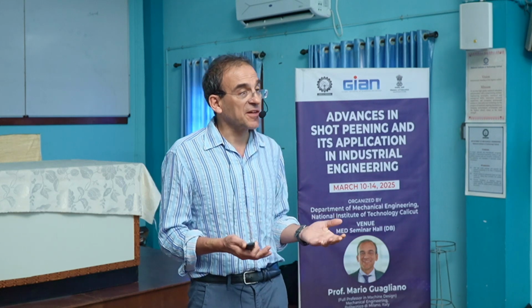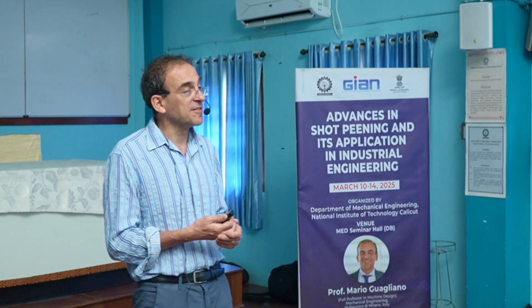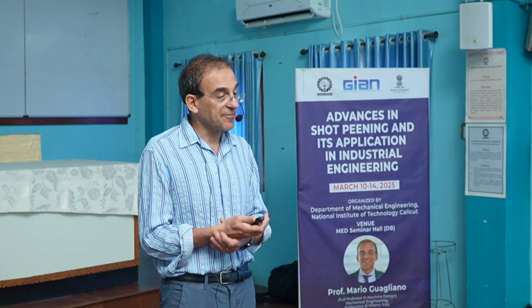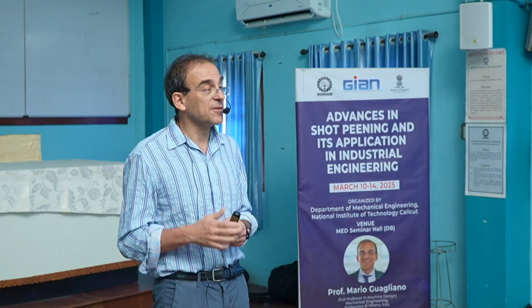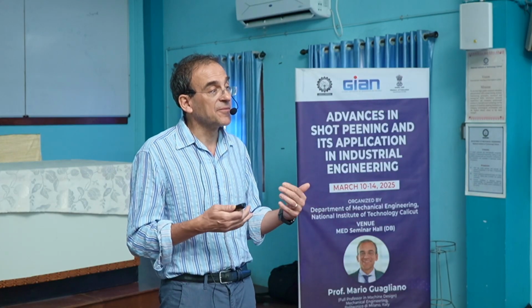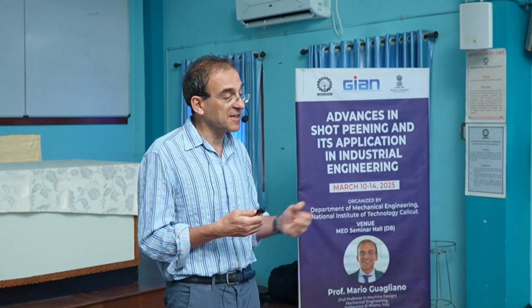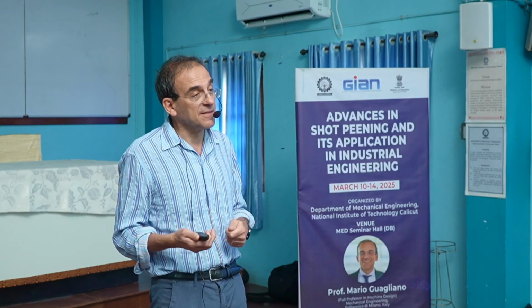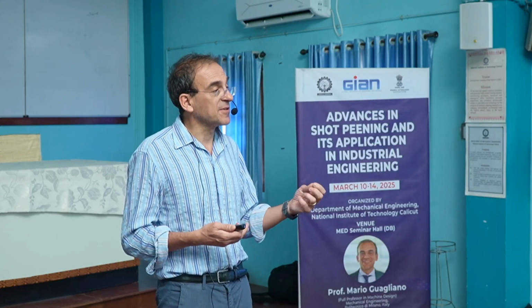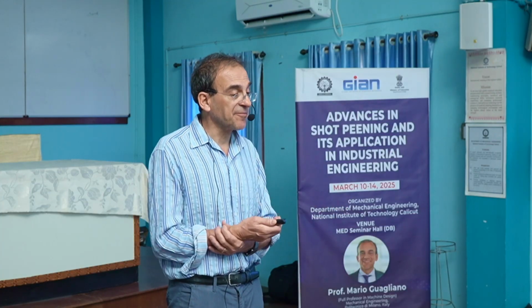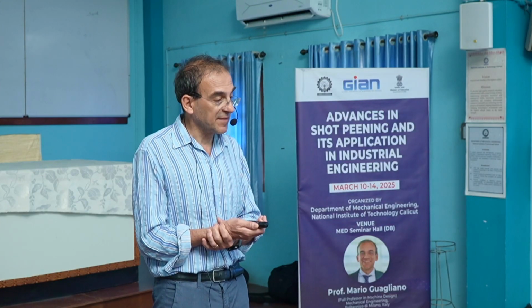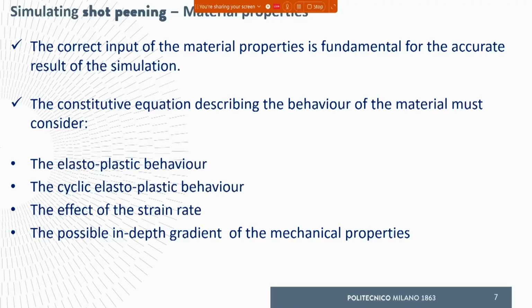Then there is the effect of the strain rate, at least in the cases where the strain rate cannot be neglected. It can be neglected both when the material is not sensitive to the strain rate, and in the cases where the strain rate is not important because the treatment conditions are too soft, let's say, to have an effective strain rate influence.